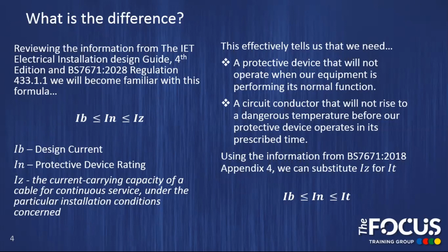What this formula effectively tells us is we need a protective device that will not operate when our equipment is performing its normal function, and a circuit conductor that will not rise to a dangerous temperature before a protective device operates in its prescribed time. Using the information we can gather from BS 7671 Appendix 4, we can actually substitute IZ for IT.